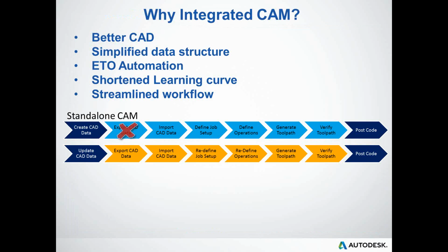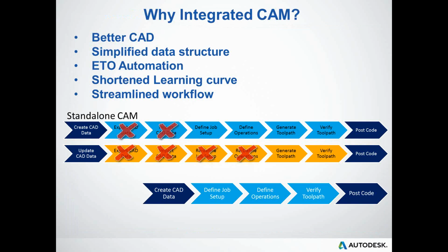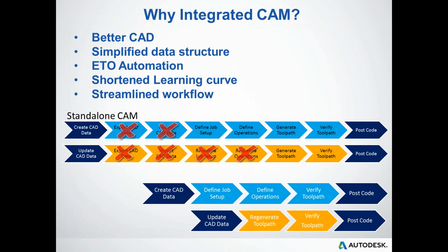With the integrated CAM, we can eliminate many of these steps and actually streamline the workflow so that as the CAD data is created, we define the setup, and I'll get into a lot of this, the operation, verify the toolpath, and if there's a change, it's really kind of a no harm, no foul, because we just simply open up the IPT or the IAM file or the SolidWorks part or assembly, and we generate the toolpath.